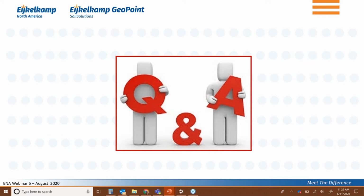Having said all that, you cannot expect that the cone will continue to go vertically down. It is very common that it will deviate as you get to greater depth. The ASTM standard allows that. The ISO code allows that. And since the inclination is being recorded, you can always make adjustments to come up with the actual depth where you are. But basically, by leveling your truck, you have a good starting point.